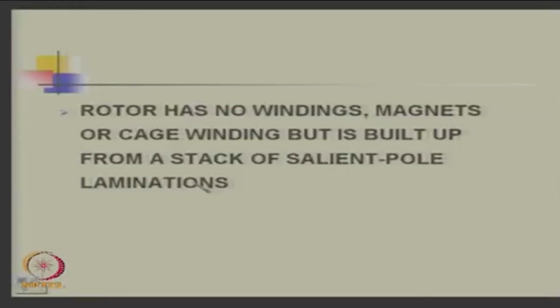There are no windings in the rotor, no magnets in the rotor and no cage windings, but it is built up of a stack of salient pole laminations. They are also laminated because again you have to prevent eddy currents, etc. So it is not a solid rotor incidentally.